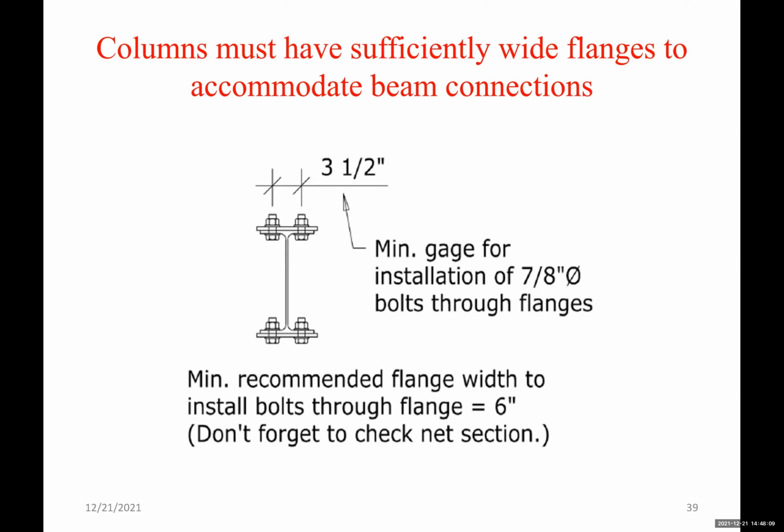It's not just, for example, going from W8 to W10, but also selecting a column size. Okay, pay attention to bf. That's the width of the W section. Okay, that's where the connection will be. Choose a section that can accommodate the connection.